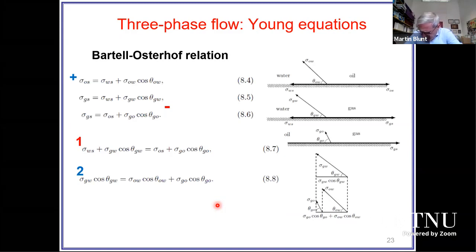What about 3-phase flow? And also, there is a little bit of a subtlety. When we're talking about surgical masks and fuel cells, we're talking about air-water systems or gas-water, whereas with rocks, we're talking about oil water, and then we're talking about plastics that clearly are sort of oily. So let's just look at this. If we have 3-phase flow, there are 3 Young equations that we can use, because there are 3 fluid pairs. So these are the 3 Young equations, relatively standard stuff.